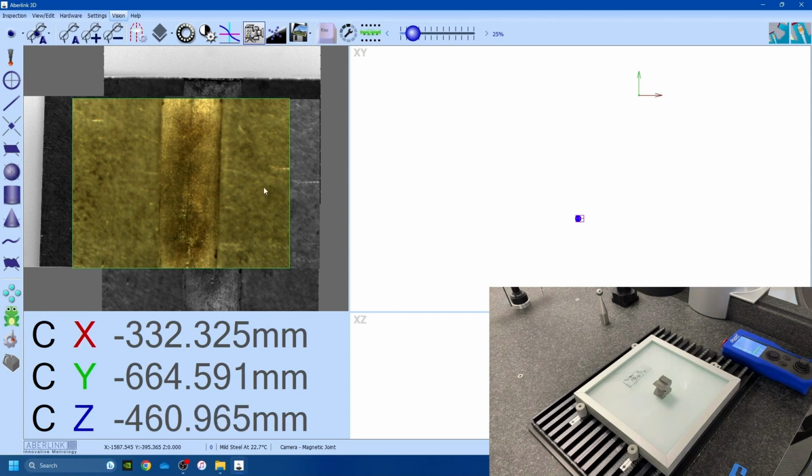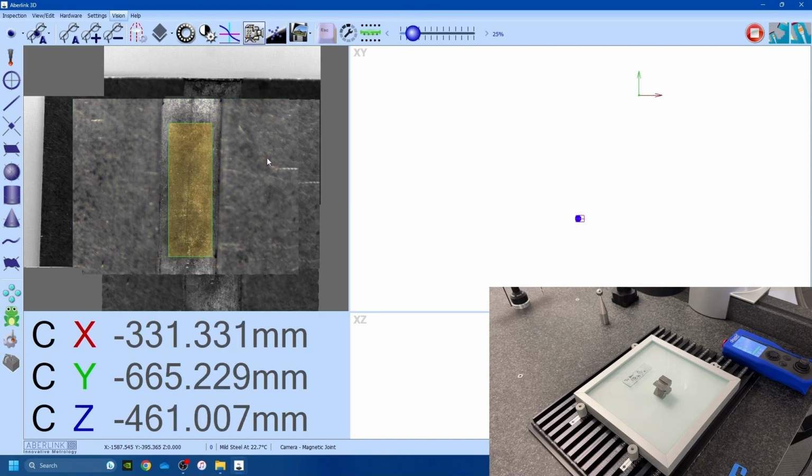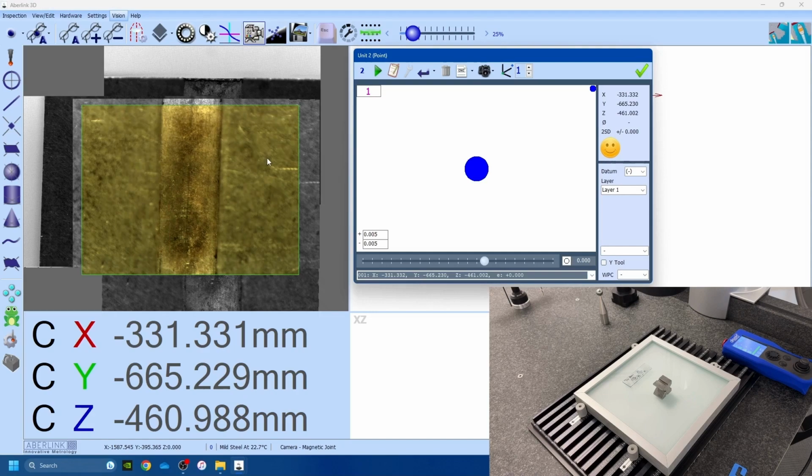So something like this. Again, we click a point, we move down as much as we can, and then to the edges, click again. That will initiate the autofocus. And again, when the software has analysed and got the focus as good as possible, it will register a point, write that into the software, and we can get the height differential from the 2 points. So there we go.